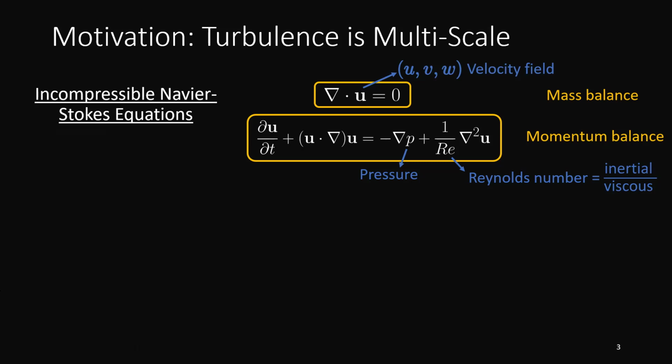And this evolution equation can be parameterized by this Reynolds number. In principle, you can think of this Reynolds number as a bifurcation parameter, for those of you who are familiar with that, wherein if you increase the Reynolds number, you increase the nonlinearity of the system, or increase the degree of chaos in the system. Specifically, the Reynolds number leads to an increase in the separation of scales.